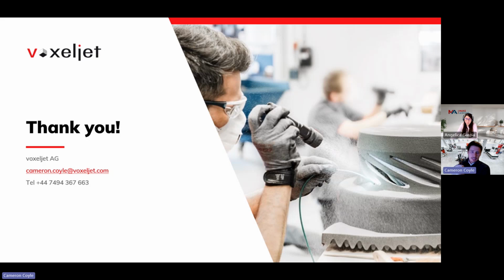In some cases, for the 4x2 meter machine, we print some very large cores for some customers where maybe only 2 pieces fit. So it might only take 1 or 2 hours or so to remove these parts from the platform, clean everything and put it back. If you have a smaller machine, such as the VX1000, and only a couple of molds, you could be talking about 20 minutes or so to get the parts out. So it depends very much on what is in there. But the idea is at least to operate with 2 boxes and be able to print and utilize the equipment whilst you do the unpacking. So your employee can work on the parts whilst the machine is printing the next set of parts.